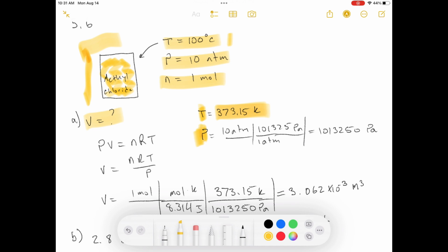I made a mistake on that in the last video, and I put a pinned comment in there. So just so you guys know, if you didn't do that problem, go back and look at that one and just mentally correct and say, oh, that said gauge pressure, I need to add an extra atmosphere on top of that. So if they give you a gauge pressure, make sure you add an extra atmosphere to that. In this one, they didn't say if it was a gauge pressure, so you assume that it's absolute pressure and go from there.